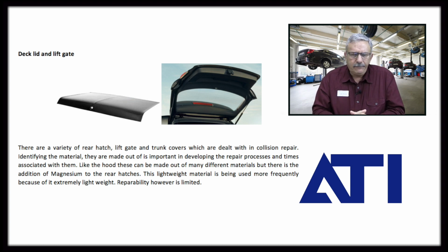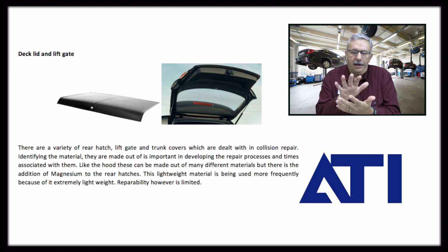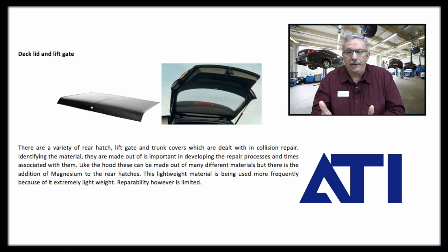But a couple of things with these, the lift gates that you'll see. We've got to be very careful now because these are another part that we're using either composites as a structure or magnesium as a structure with aluminum on the outer skin, sometimes high-strength steel on the outer skin. Why does that make a difference? Well, it's a huge difference when you're working on a part that has a magnesium frame. There are some very specific repair parameters. Actually, there's not a whole lot of repair you can do.